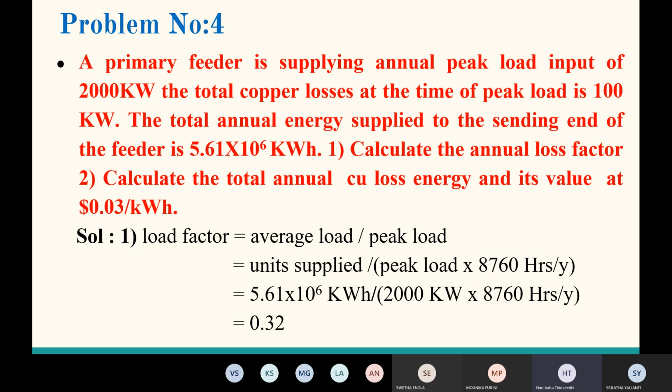5.61 into 10 power 6 divided by 2000 into 8760. So the value of load factor FLD is equal to 0.32. Now determine the loss factor by using the approximation formula.